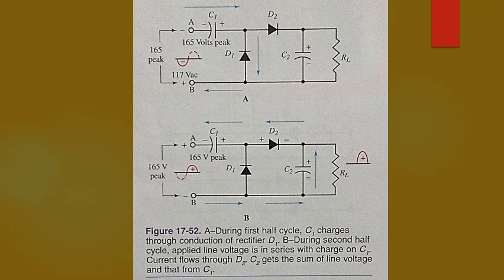(17.5) Voltage doublers. Up to this point, it has been assumed that the source of power was 117 volts AC, found in homes and schools. The transformer was used to step up or down the voltages required for the electronic circuits. Because transformers are heavy and costly, voltage multiplying circuits have been devised to raise voltages without the use of transformers.